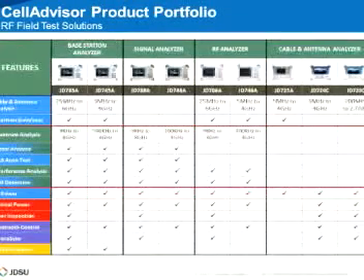And we have products, again, on the cable antenna analyzer that have different frequency ranges, but also some have single port for reflection, return loss, distance to fault, but others have two-port, which are excellent for characterizing literally anything that has two RF connectors, including if you have a repeater, a donor antenna as well as a receiver, a serving antenna. You can measure the isolation, very similar to taking a microphone and putting it in front of a speaker. You don't want unnecessary feedback loops on your RF system.